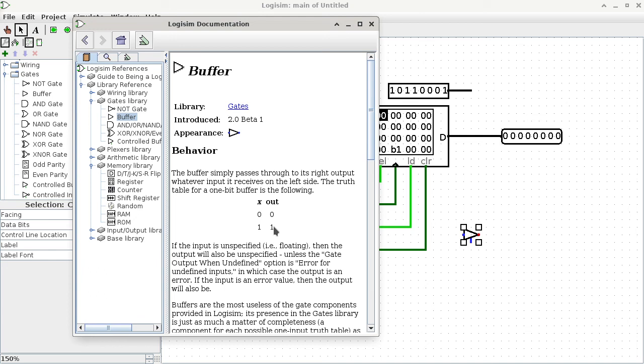On the other hand, if you're actually building a circuit with a huge fan out, a buffer is useful. The output of one thing, like a NAND gate, can physically only drive, let's say, 6 inputs. So you can only have one output pin connected to 6 input pins, and beyond that the circuit would behave in a weird way.